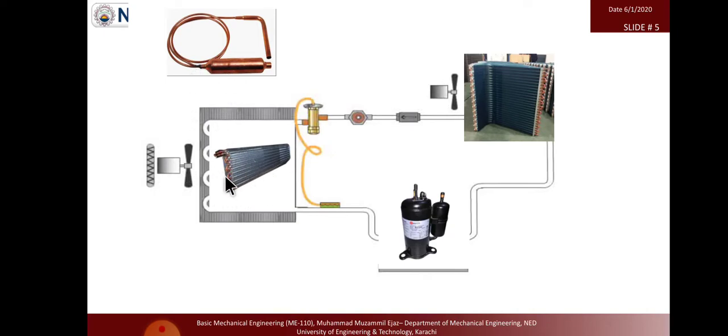So the air is cooling from this point, and again the refrigerant will not decrease its temperature, it will decrease in the expansion process. When the refrigerant comes into the evaporator, the phase change occurs again. The liquid refrigerant has a very low boiling temperature.